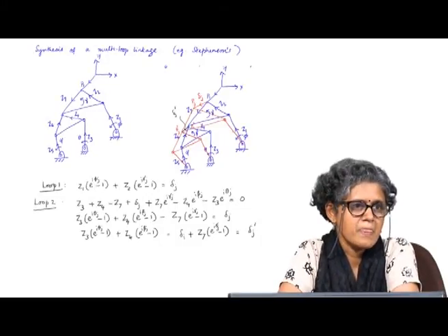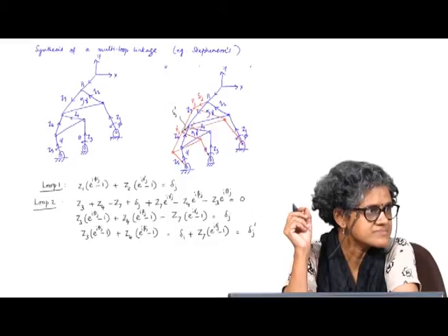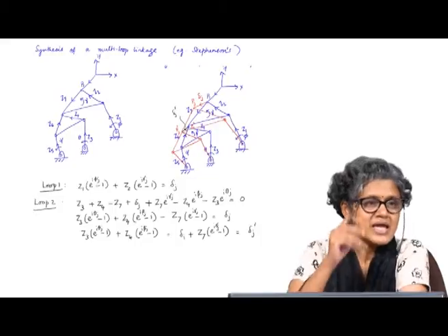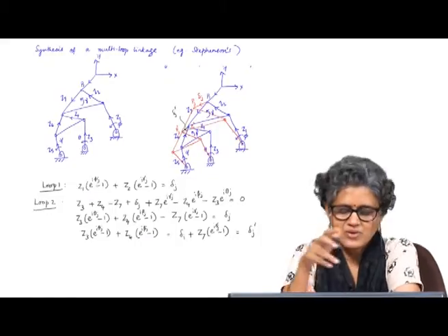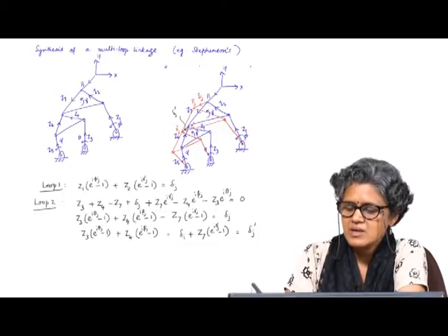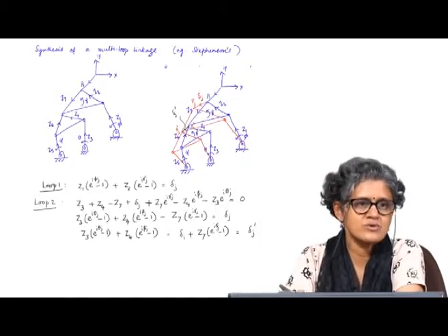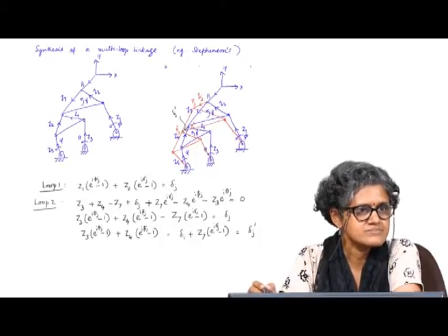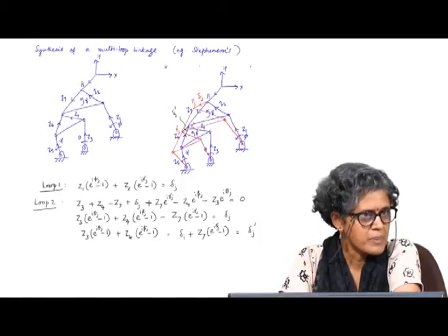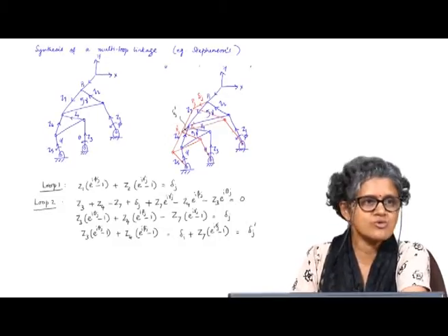See that? It is the displacement of that point p1 dash. Okay. So, now what happens to my equation? If I pick z7, I know gamma j. So, if it is a motion generation problem, say I know the locations of p1 or the delta j's, and I know the gamma j's, the orientation of this thing. Now, if I choose z7 as a free choice, this becomes known.